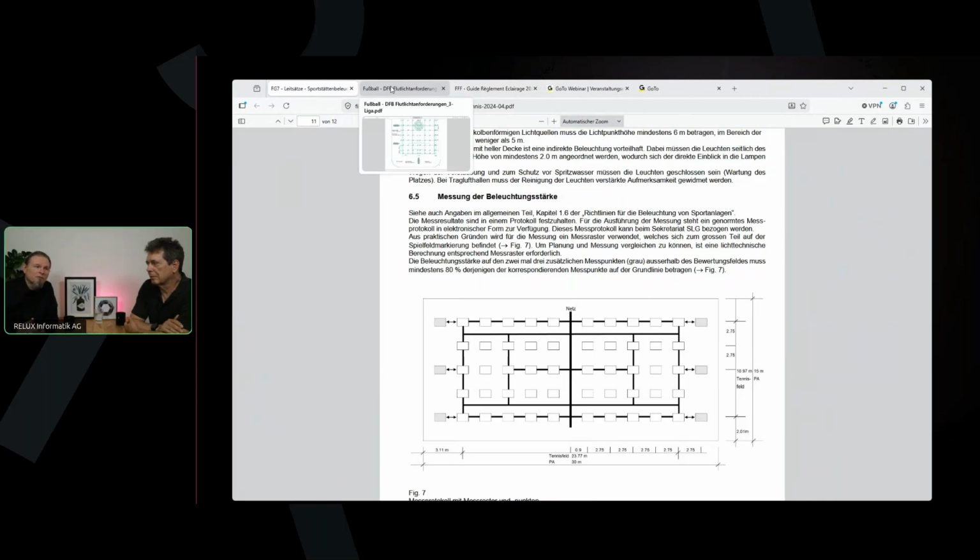For example, if you get a support case where some users are not happy with the result, or complain that it's not the same as in the last version or on a competitor's software, then one of the first things you need to check is the grid. Check if it's the same grid size, whether it's denser or wider, and whether it covers the points where you're calculating or measuring. The grid is really important for the precision and accuracy of the values, and for the values in general.